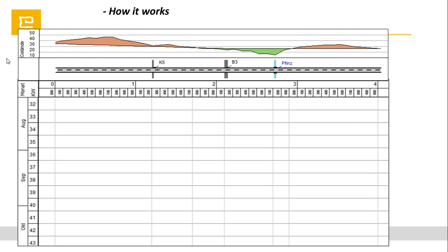This is a road project, and here you can see that my project start location is 0 and my project end location is 4, and you can see the roads, and we have a road crossing here. Road crossings are important because if we have a road crossing on the path of our project, we have to pay attention here. Our performance can be lower. We need to make some protection. We need to do some special works, and that's why the project work rate, the performance work rate, can change.